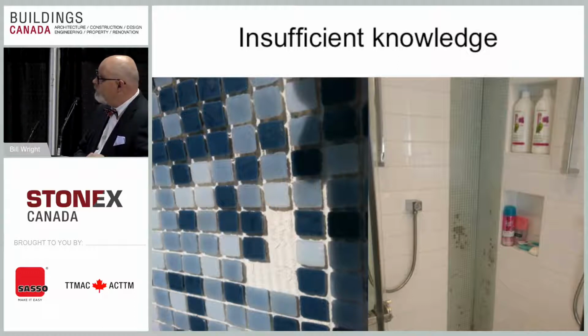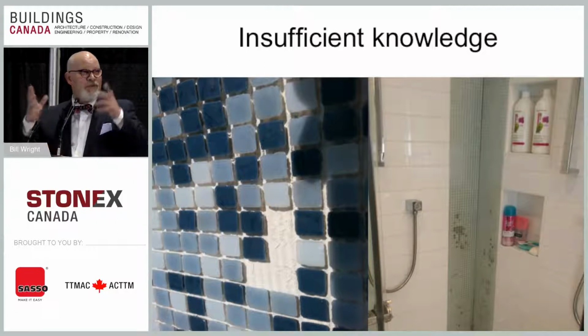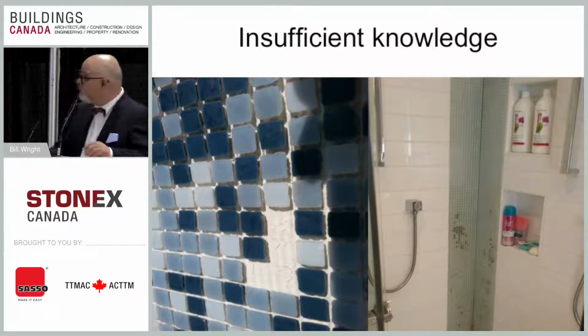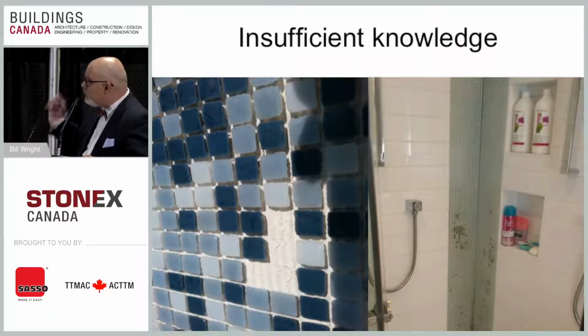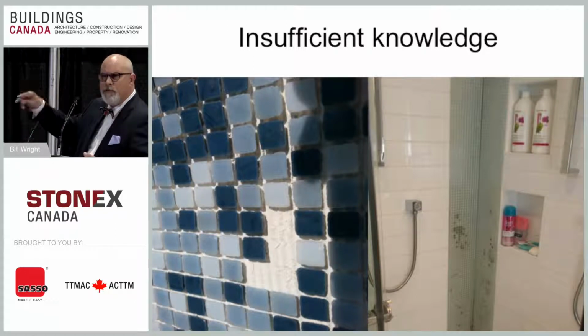The poor guy was desperate. I think he managed to find somebody to remount it to get it reinstalled. But you were talking $30,000 worth of glass tile that was just going up and coming down because it wasn't being installed properly. The one on the right, we generally like to use either epoxy or sanded grouts for wet areas, especially behind mosaics of stone and glass. This is an installation with unsanded grout. And it wasn't sealed, so the moisture's getting in through the grout joints and discoloring the glass tile behind it.